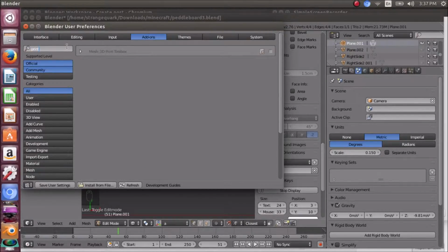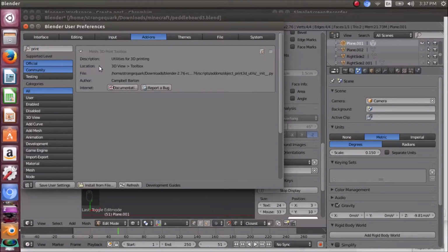That's an excellent tool, especially if you're using it in edit mode. It'll analyze your mesh and tell you what's wrong with it, the things that you need to resolve when doing a 3D export from Blender or getting it prepared for an STL export.